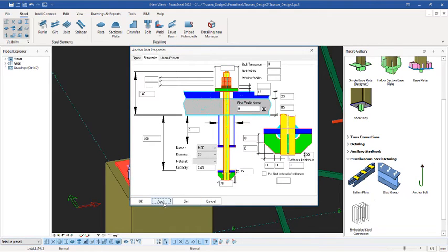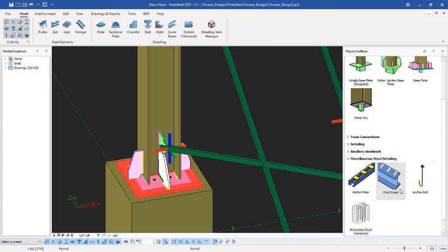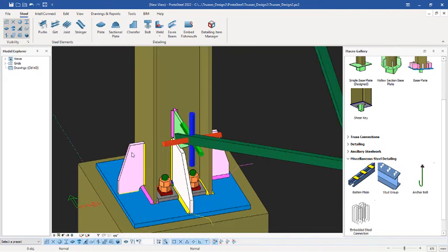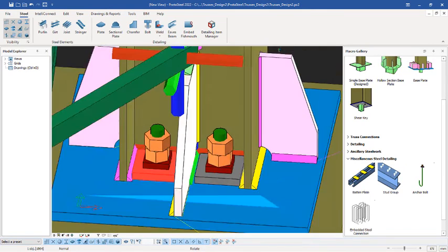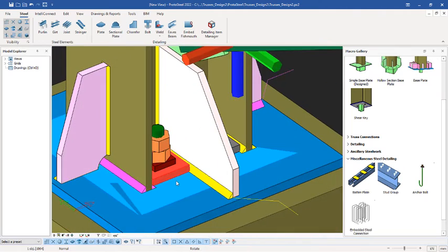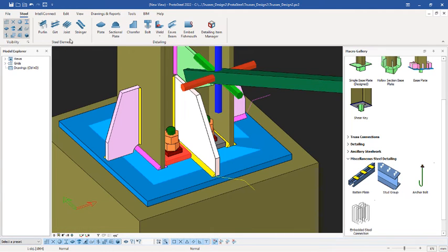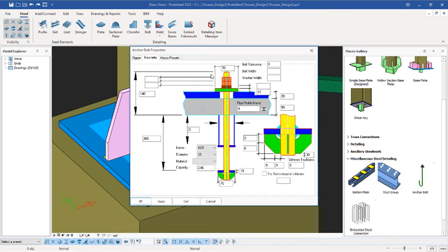Get, apply and okay. So now just select this, right click, and then select the plate to insert this. So you notice the bigger washer is still being inserted, which I wouldn't want. So you can undo that to get rid of it. Then right click on this again, get back here. This 70 is what is causing that. I'll change the 70 to 0, come over here, change it to 0 again, just like this, and you can apply it and okay.